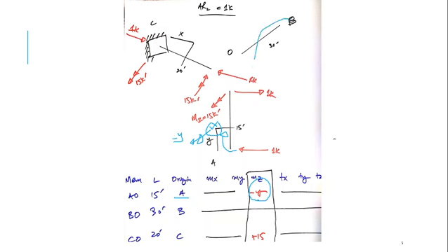Member BO is all empty, so there would be no moment. Now coming on to this member, this is my X. I have taken this section X. I have to find all moments here. At the end of this section, this 1 kip is in X direction and this section is in X direction, so there would be no moment because of this 1 kip. However, this 15 kip foot is anti-clockwise. It should be balanced here. 15 kip foot.